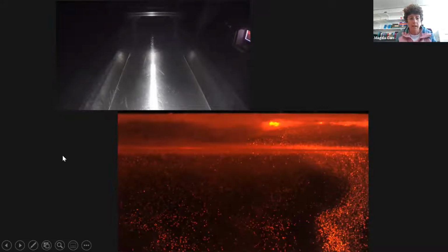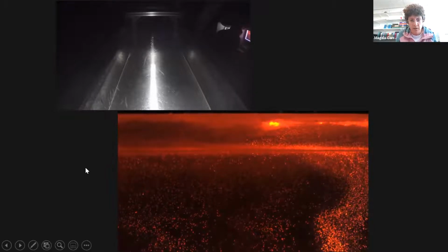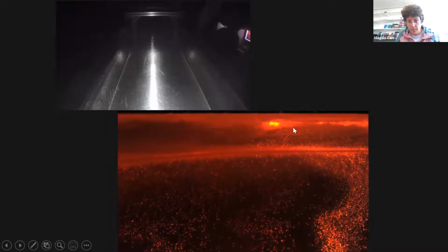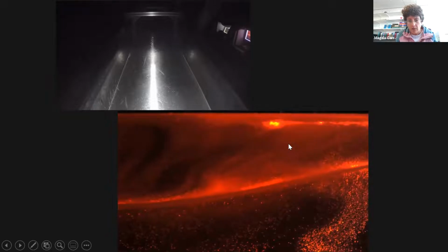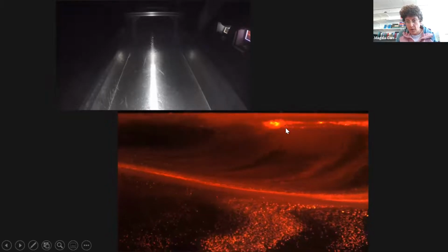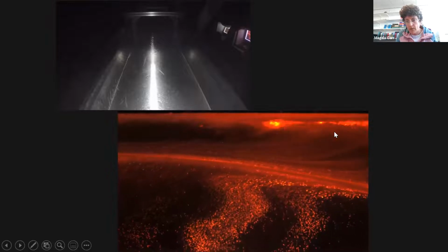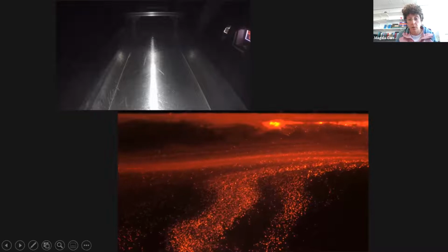So in this case, the ice wasn't free to move. It actually went right the way to the edge of the tank, so you're not going to see any transport of the ice. But if you look closely, we've got roughness at the underside of the ice. And you can see as the wave goes past, we get small scale vortices forming at the underside of the ice and turbulence generated there as a result.